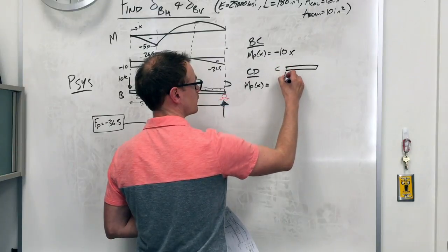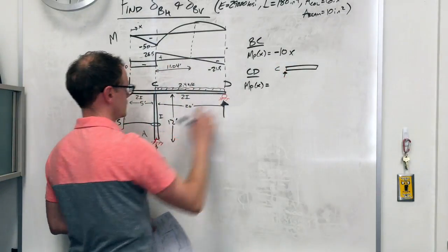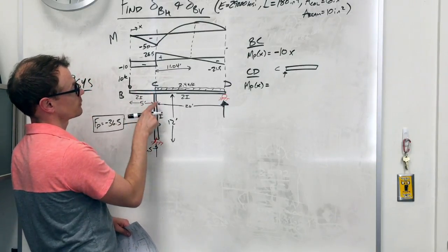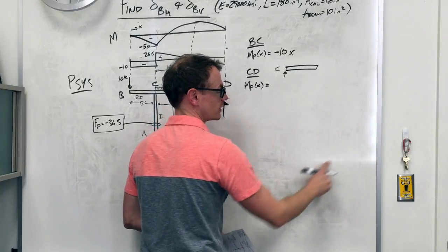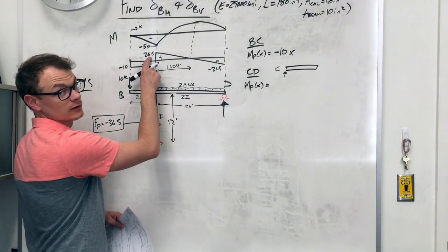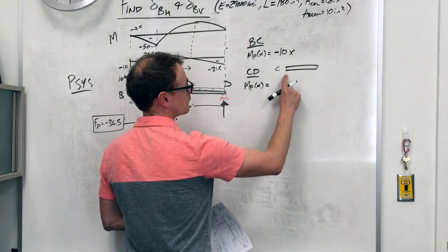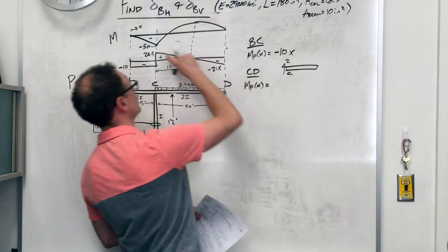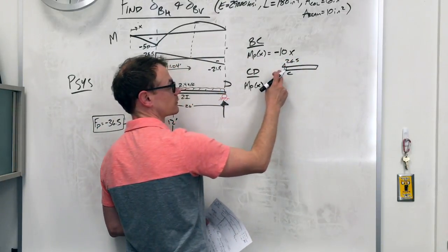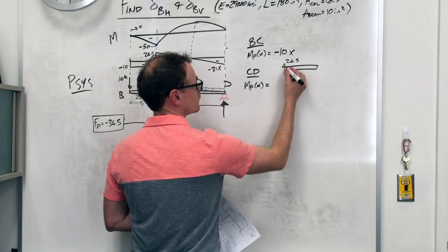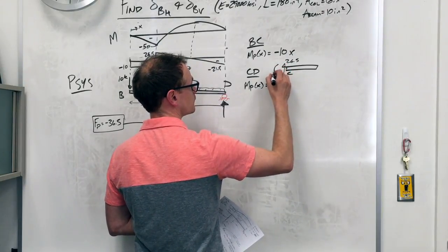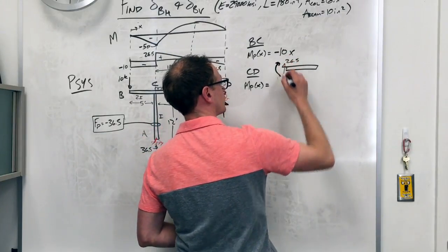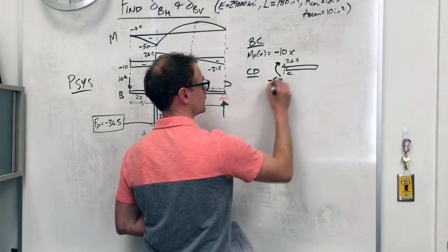this is point C, this is kind of a reaction, right? Comes from this axial force and then was reduced by 10. If you remember, I drew the joint equilibrium here, but also you can just look at the shear. The shear tells you the internal force here, right? This is point C. This is 26.5. That's the internal shear right at point C. And then the internal moment was, I'll do the correct thing there, minus 50, like that.